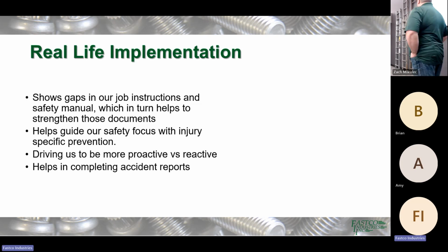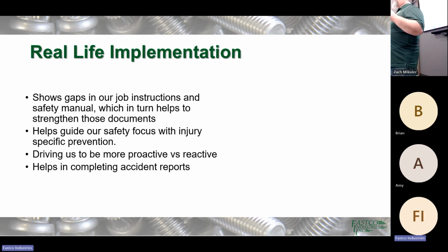There's some that we put in there where the RPN didn't change after we did stuff, but it still made it better. We still did stuff to make it better, it's just still in the same RPN area. In the field they ask, can you get your RPN lower? I'm like, really, we can't, because what we're doing is what we're doing. In our field, for the severity, you're going to have scrap. You can't rework fasteners very often. As a company you want to set, okay, anything over this, let's really focus on it, but you need to use those numbers to your advantage, not just pencil push them down.